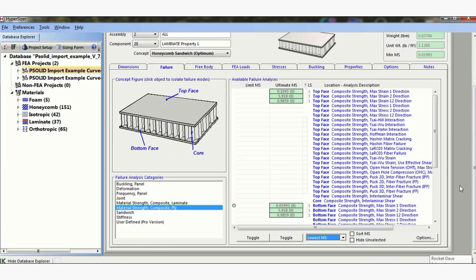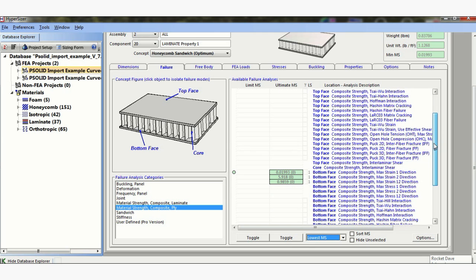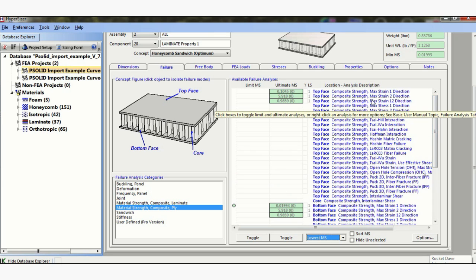But just giving an example here, I'm doing some composite analysis. A lot of people use ply analysis, even though I really prefer laminate analysis, but most corporations use this ply by ply, which I think is kind of wrong because we have damage requirements, and I don't quite know how you figure out damage on a ply by ply basis. I think it's fundamentally flawed, but it is what it is, and it's what we do.